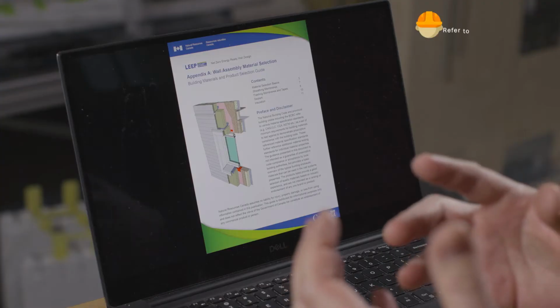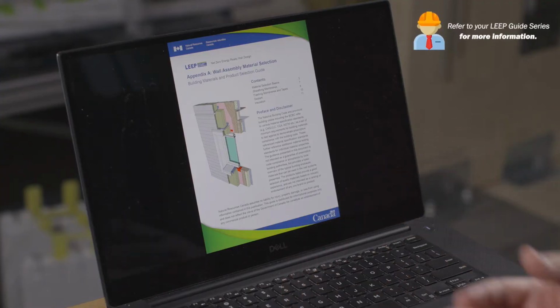Okay? So when you look at materials under the building code, we are governed by a number of standards. When we're selecting appropriate materials for air barriers or insulation or sealants or tapes, it's important they do their function. Air barrier materials need to stick to each other, and they may be from different suppliers or different manufacturers. And so it's critical to pick sealants and tapes and membranes and things that are all compatible and that are going to stick and last the life of the building.